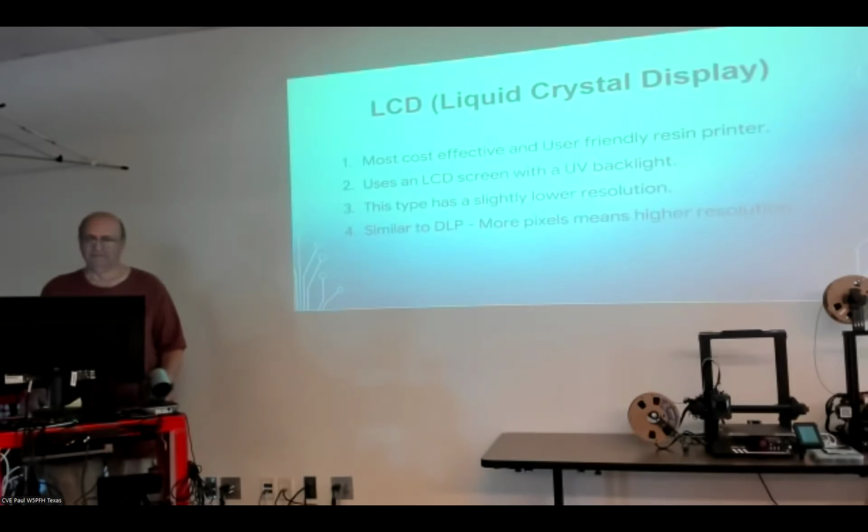And then most of your resins are UV cured. So you print it, you put it through the acetone bath to smooth it, and then you put it in a curing cabinet to finish the process. The acetone, it's just gaseous, right? Yeah. Right. The upside to the FDM is when it prints, it's done. You don't have any of that post-processing to be able to have something that's usable.